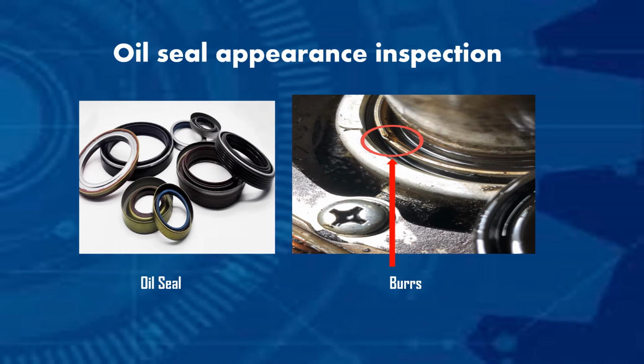Oil seals are composed of various natural or synthetic rubber compounds. Oil seals dry out if not used for some time. The oil at the seal shaft interface may slowly dry or drain away, leaving the metal surface exposed to oxidation. A slightly rusted shaft burrs the seal when the parts begin rotating, so a seal in this condition may leak when driving the car. An unused seal might develop a dry spot susceptible to weathering and cracking. Sometimes the seal will swell and reseal after some period of reuse, while on other occasions the leak will gradually get worse as the seal disintegrates.